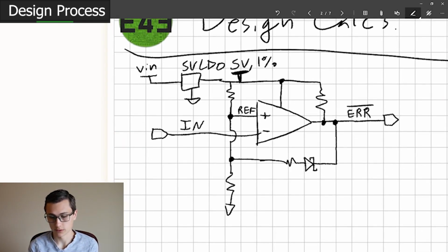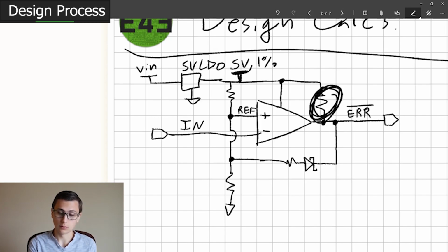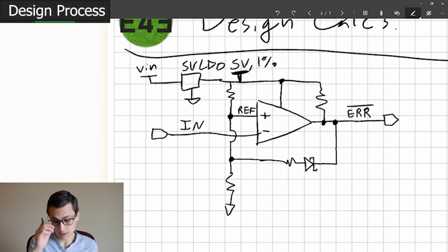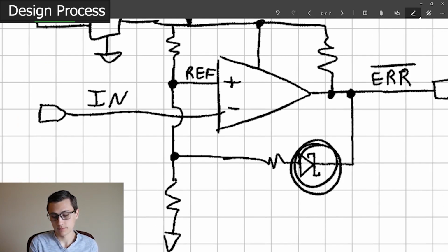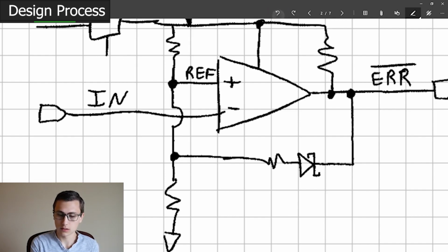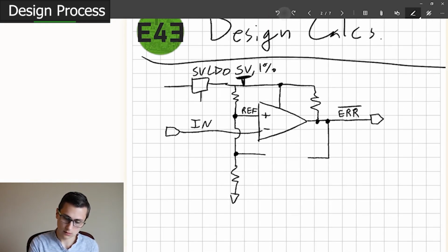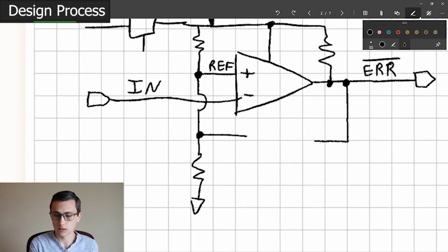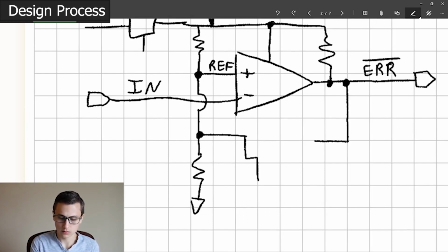So what do we want to do, right? We're faced with another design decision. Now remember, one of my goals, I don't even think I wrote it down here, but I want to be able to use multiple of these in parallel. So that becomes more difficult if we use this resistor for 2 functions, because then if we had a second comparator, that gets a little messy. So that means that in some ways, this diode would help us out quite a lot. Though we've got more choices than that, right? What we really want to do is clamp this node to ground. So in theory, we could use a FET, or we could use a BJT.